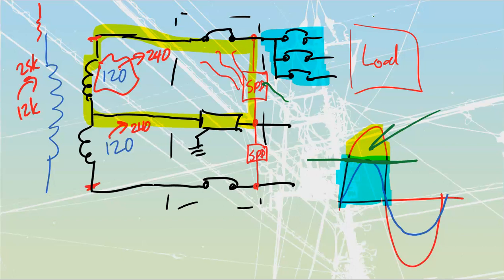And then the last one would be inductive kick. If I've got any sort of DC rectification happening inside there, and I'm working with DC components, and I don't have a proper snubber or freewheeling circuit set up with that thing, then, boom, whenever I shut the thing off, I'll get a DC kickback into my system. It's all for temporary things.